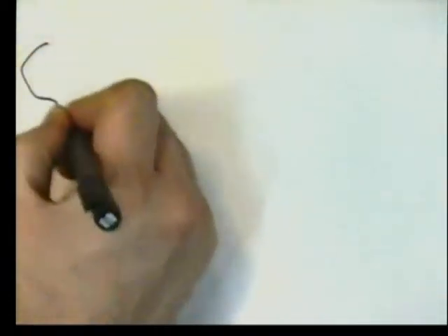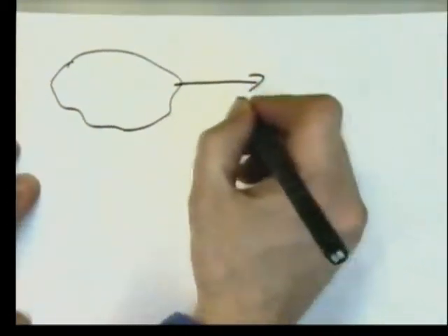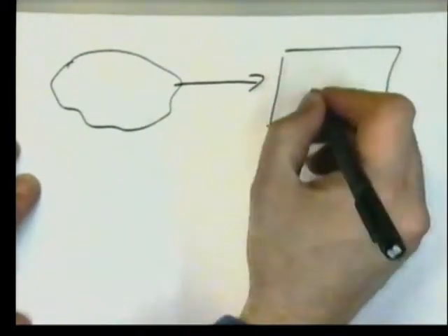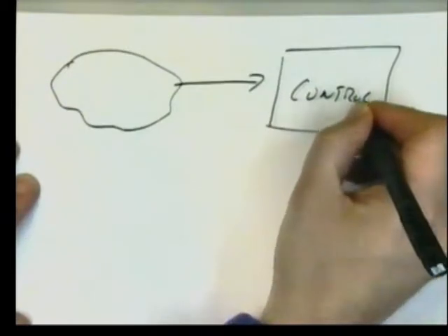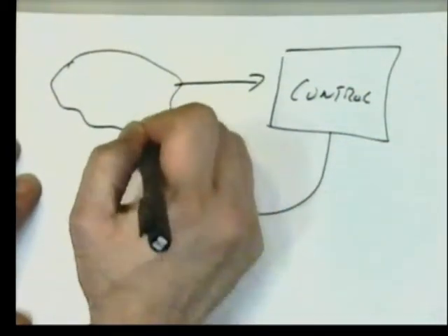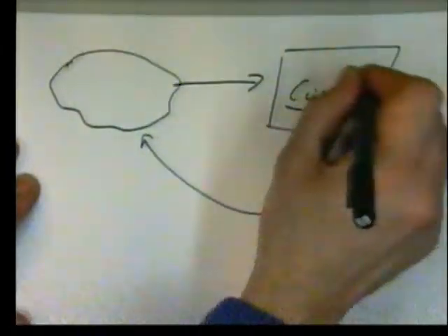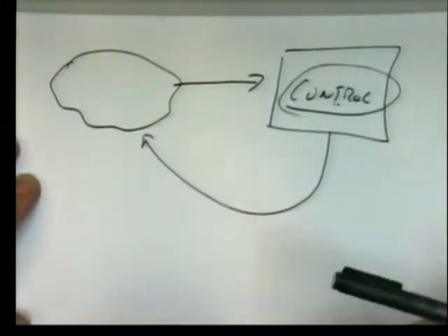What we're trying to achieve, here we have the world from which we take our measurands into our controller. We take some decisions and using actuators we try and drive the world back to our desired position. What we were discussing last time was the contents of these control algorithms. Now, the simplest algorithm you can use is on-off control. Very crude. If you are below your set point, you switch your system full on. If you're above it, you switch it off. And the response characteristic looks something like this.